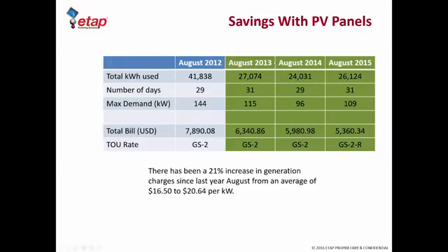And then August 2013, we plugged the system in, which is shown in green. So that's essentially when we switched over to green energy. And you can see that the kilowatt hour usage dropped significantly down to 27,000 kilowatt hours. And we are essentially on net metering. Hence, you will see that this offset or this drop is because we were producing the difference, or almost the difference of the two, and providing the power to SCE during peak summer months.